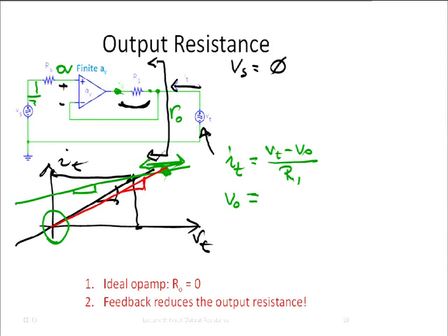Hence, if Vs is equal to 0, the voltage at the input of the op amp is also equal to 0. Okay, so what about the other terminal here, the minus terminal? Well, here we have V test. Then this is just a wire, so here we have also V test. So we have 0 minus V test, so that's minus V test times the gain of this operational amplifier, which is AV. Okay?